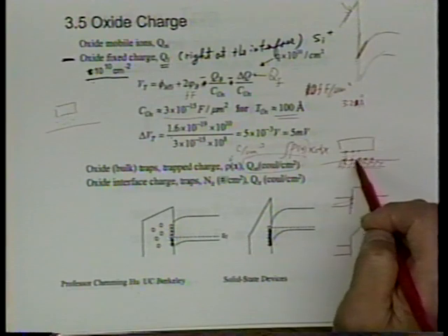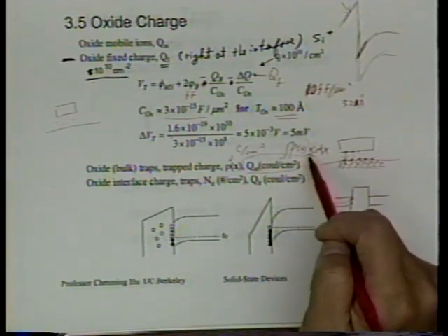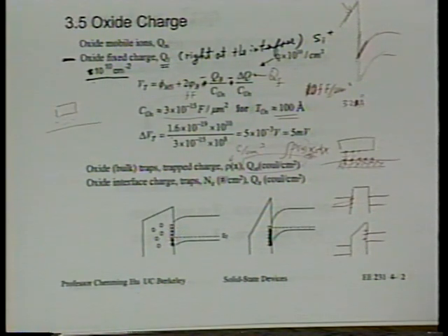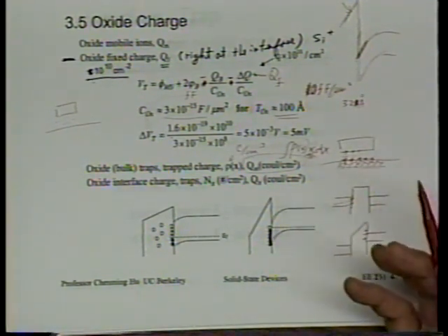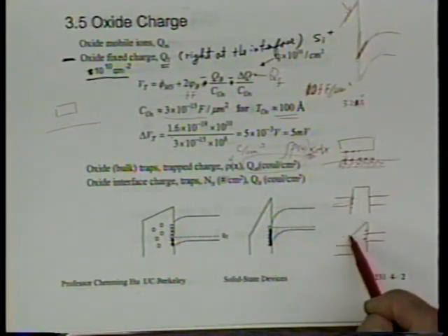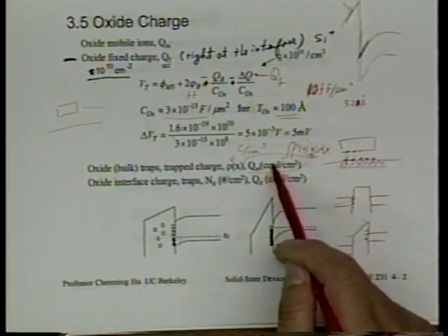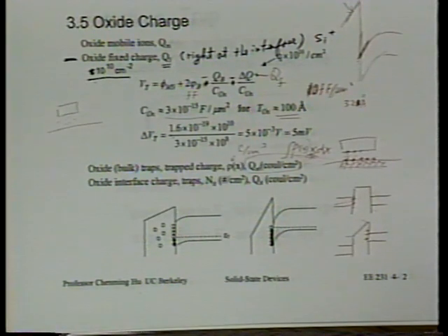Charge at the substrate has full impact. In between, it's in between. That's what this integral is about. You see what I'm saying? I just try to let you see this from one specific example. It makes sense to try to integrate this. If you are mathematically oriented, just go ahead and solve the Poisson equation for this whole curve. You will find out the voltage created by the charge density is indeed this. That's the voltage created by any arbitrary distribution of rho.